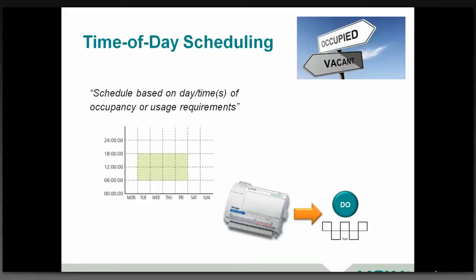The other thing you can do is it doesn't have to all go off at once. If you install this type of solution, you can schedule how that's done to shut down things in a certain order. And the other advantage is, I've seen this not only in factory environments, but also in IT data centers. Sometimes things have to come up in a certain order. You can also make sure they come up in the same order, the reverse of how they shut down, with this type of investment in a local controller. Okay, and this is typically with digital devices for on-off. But remember that you can also do analog devices if you have things that have to come up in a ramped fashion.